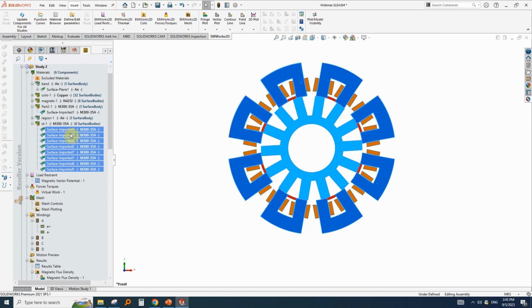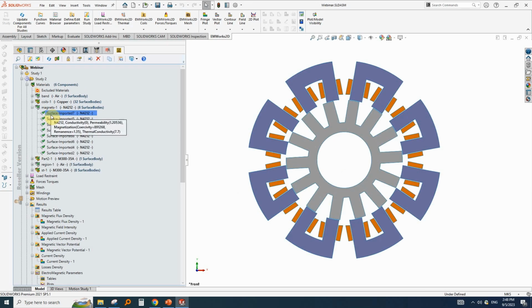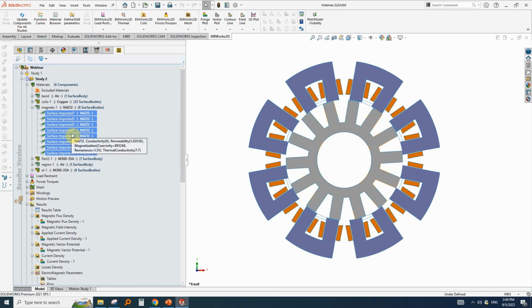After we applied all the materials to the simulation, we have to define coercivity for the magnets. To define the coercivity, first choose all the magnets, and as we mentioned in the slides, all the magnets are magnetized in the phi direction in the cylindrical coordinate system. All these magnets have this kind of flux density in the direction of the rotation, and all magnets have the same coercivity.